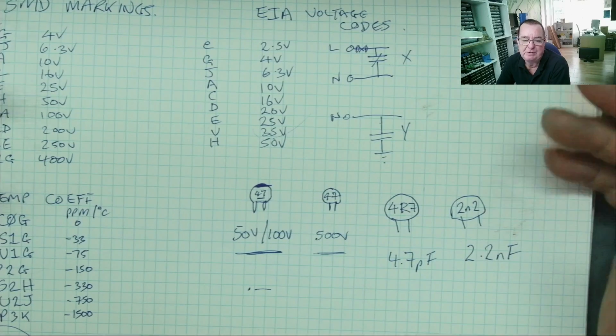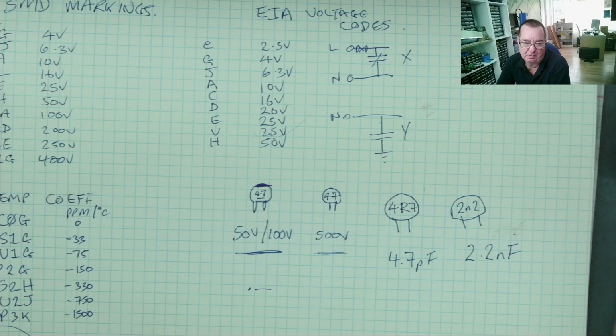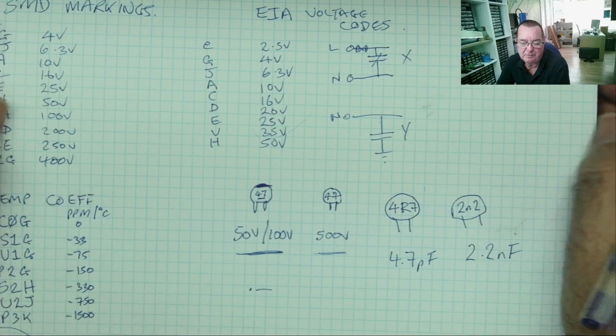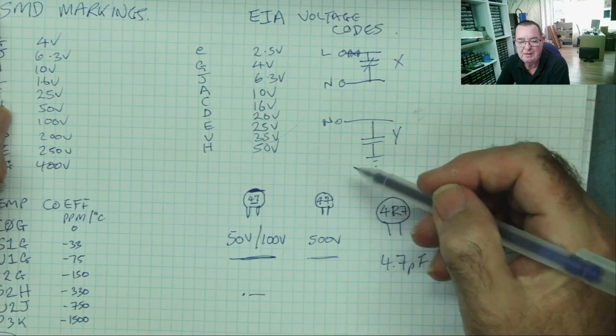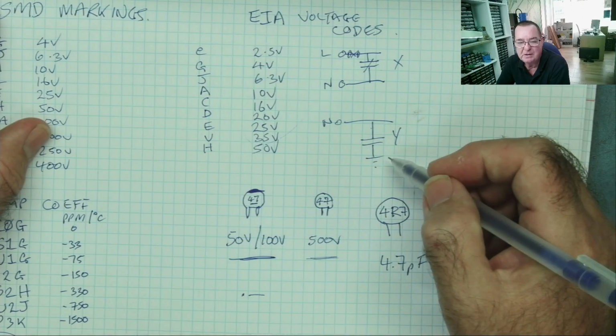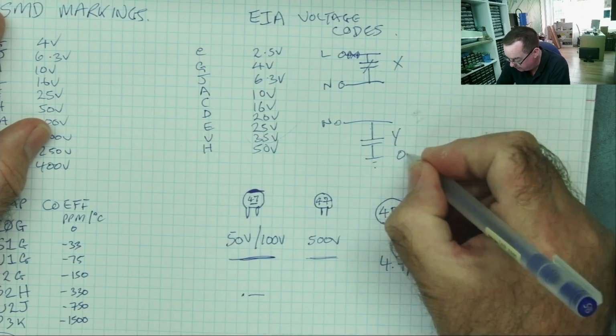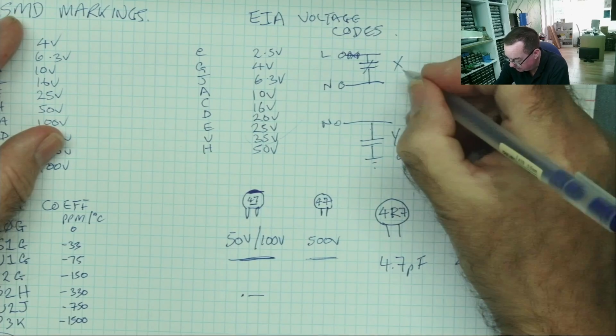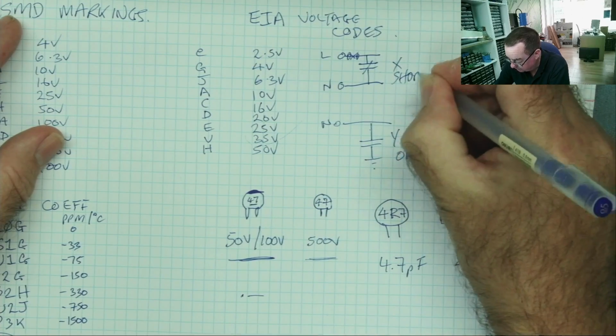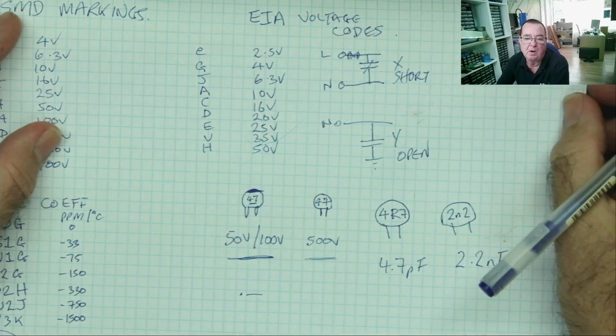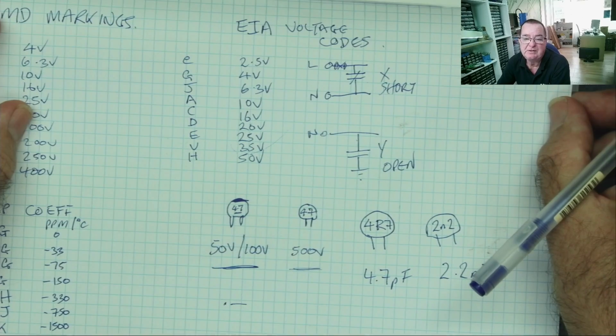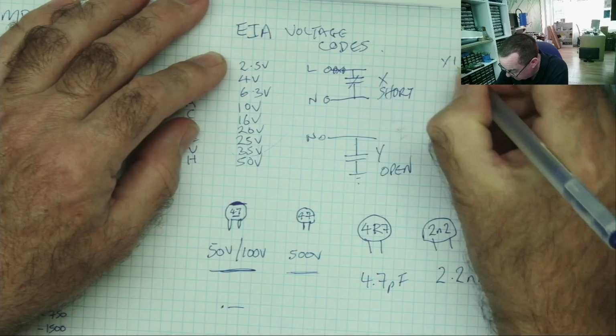And you could end up with a piece of equipment that's actually working, it's just live, with the metal working live. So to prevent that happening with a Y capacitor, if these fail, they go open. They're designed to go open on failure. These are designed to go short. So that's what the X and Y capacitors are. This X2 we saw, well, we have X1, 2 and 3, and these are subclasses.